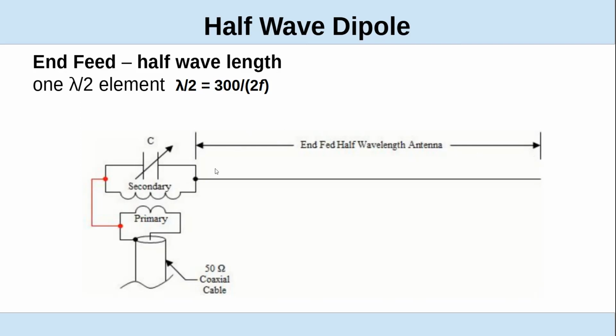You're just feeding it differently and you get different effects as far as the harmonics that it resonates at. And also the impedance is going to be very high. So you're going to use a 49 or 64 or something to one transformer. They'll be ununs technically because they're unbalanced to unbalanced.